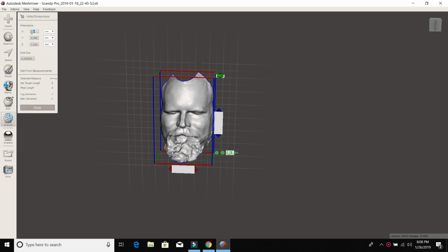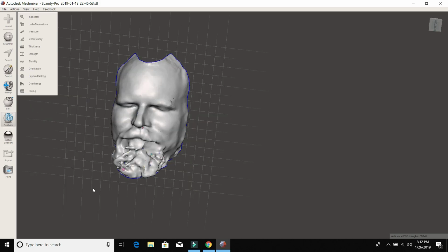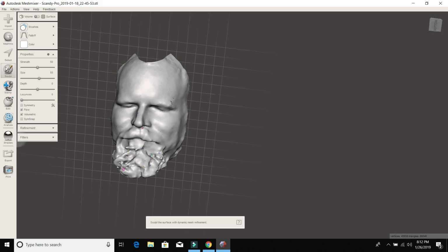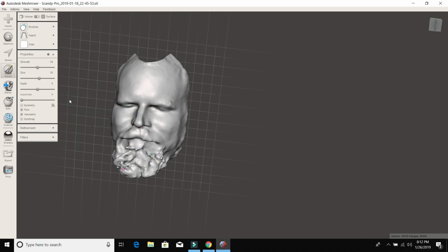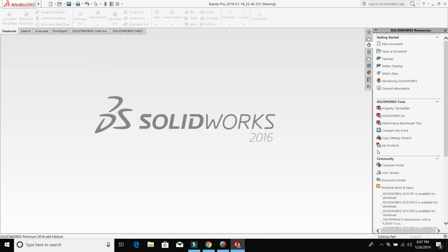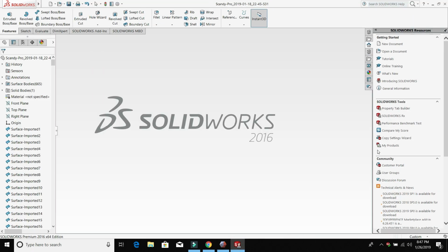So you're going to want to resize your image in here to match your print bed area. And also you don't want to export out of this software with really small settings, because if you blow it up in your slicing software, then you're going to lose a lot of resolution on the image. So you're going to want to do any adjusting in here so you keep all your resolution. And I'm using the tool to smooth it out.